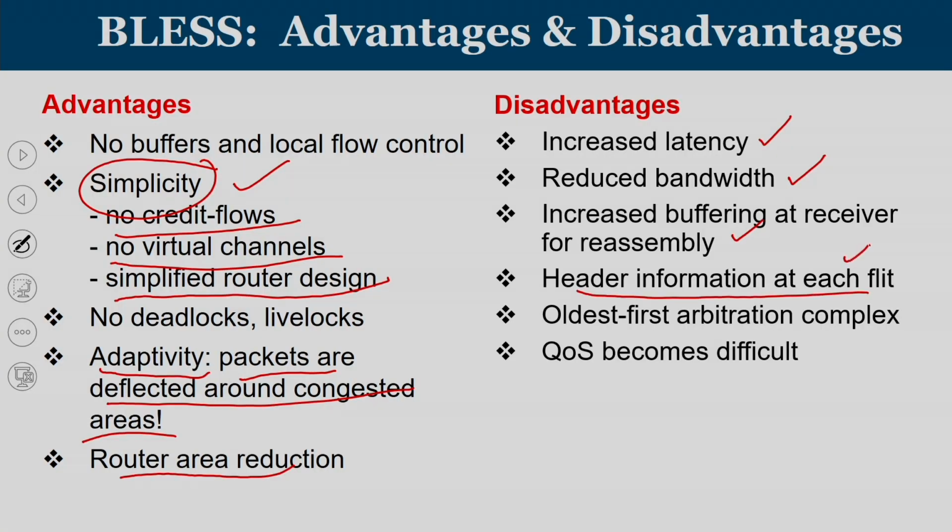So that's what I mentioned. Since each of the flits is independently routed, there should be a mechanism which will help us to ensure that some basic information is available regarding routing. That means basic header information should be available in each of the flits, and this whole setup works with finding out who is the oldest flit in the system, and it is being given guaranteed progress in the productive port.